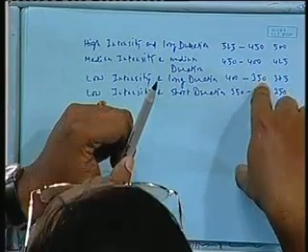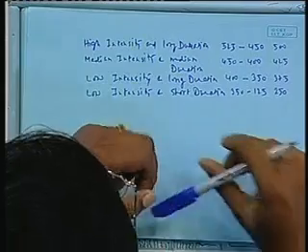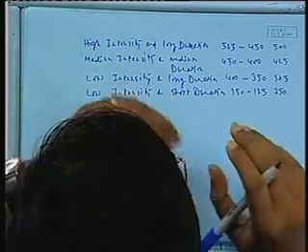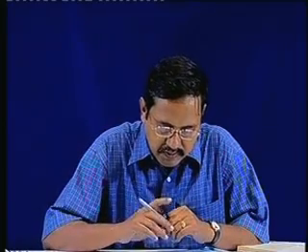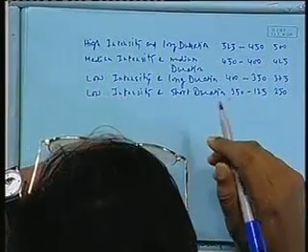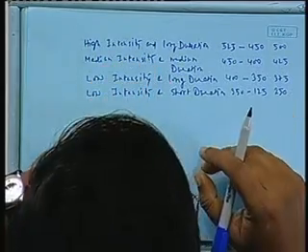In India, the Andaman Nicobar area would have the highest rainfall, and as we go towards the west, the rainfall comes down. From the iso-erodents, we can find the value of the rainfall factor. If it is given in a problem and you have to start with a value, for high intensity and long duration rainfall you should select R equal to 500. This is the starting value.